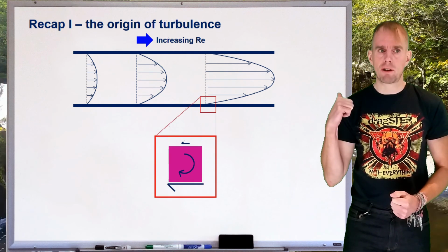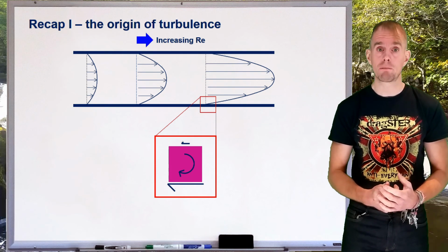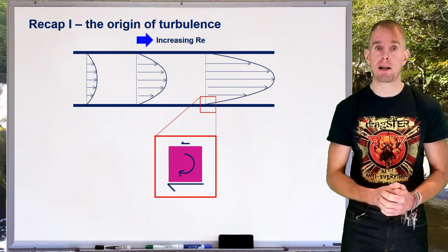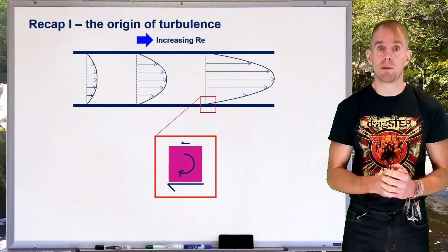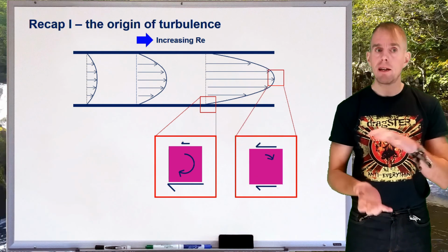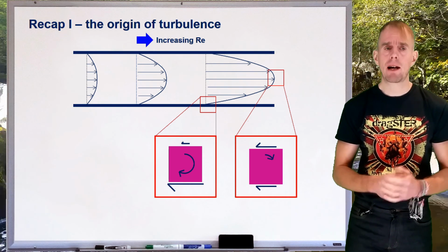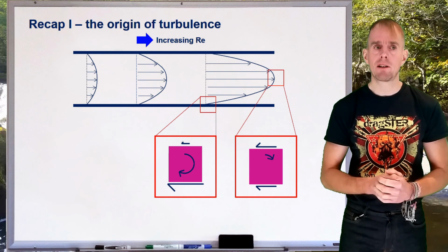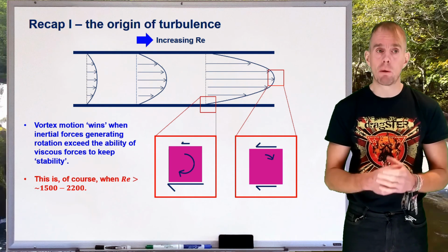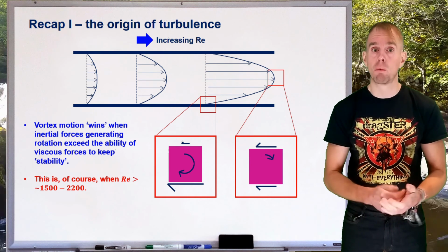Let's examine this most stretched velocity field and look at what the force imbalance looks like on our element of fluid in 2 locations. Let's look firstly close to one of the walls, and this is where we're going to see one of the greatest shear stress imbalances. And so the moment induced on a fluid here is going to be very, very great. If we look closer to the symmetry line, the imbalance is going to be less, and so again the moment will be less. If we keep stretching this velocity field, at some point rotation is going to win. And what you find is that rotation will win at the point in the flow where that shear stress imbalance is greatest, which is going to be close to a wall.